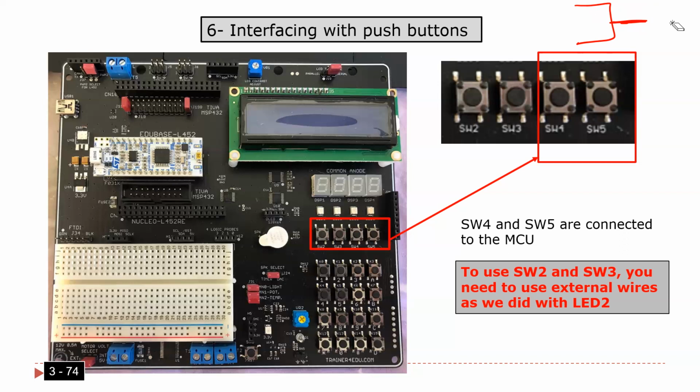You should connect an external circuit somehow. There should be an external circuit. The external circuit should put 0 volt or 5 volt here, and then the microcontroller has to read the pin to see if it's 0 volt or 5 volt. That's it. So there should be some external circuit to put 0 volt or 5 volt. Is that clear? Let me give you details.